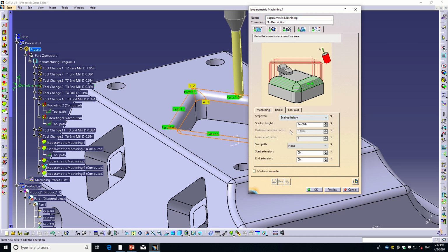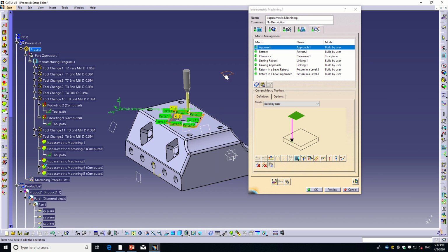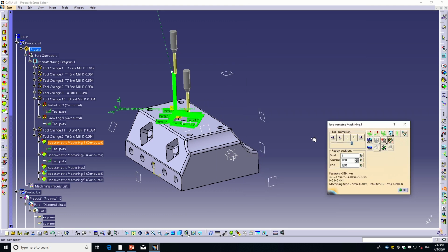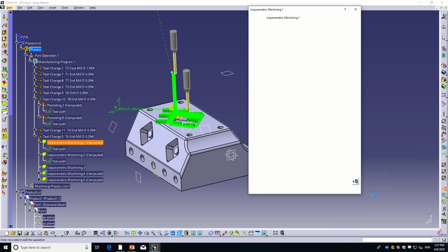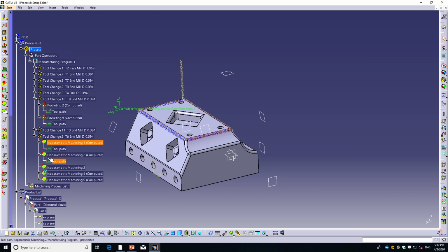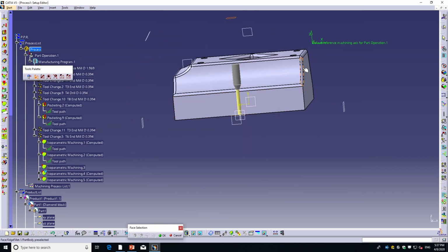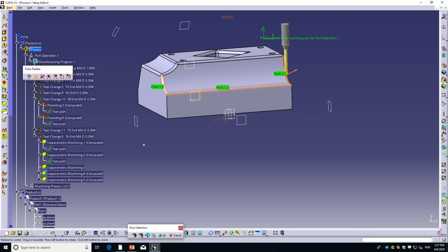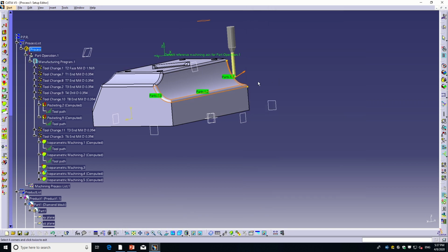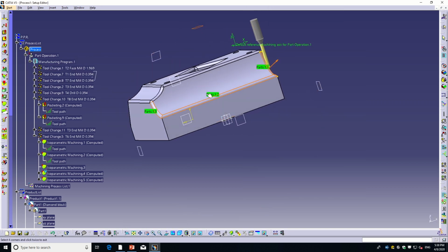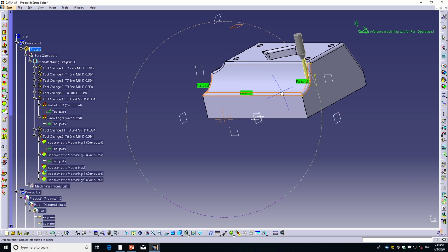Don't forget to check the radial tab and use the top plane for the macros. Calculate the toolpath. Lastly, I will show you how to do the curved backside of the part. Click on the sensitive area and select the rounded corners. Double click when done. Next step is to click on the red dot in the sensitive area.